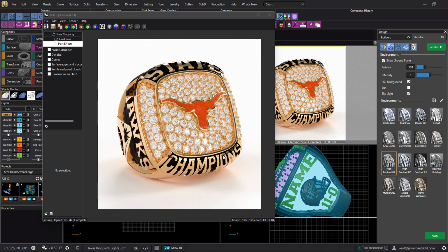You can see this highlight right here and so on. But I can't tell if all of them are or they're just not receiving highlights. But I have a trick for that we can do as well. And it's not going in and showing you how to fillet every edge. That is a trick, but I don't know if it's one that always works in Rhino. Fillets can be finicky.